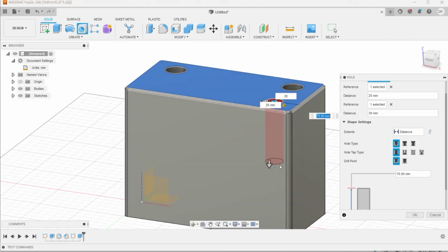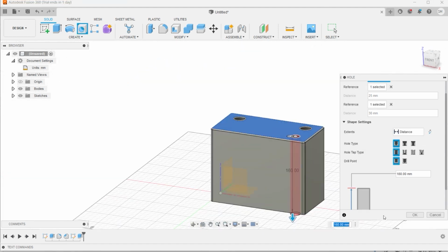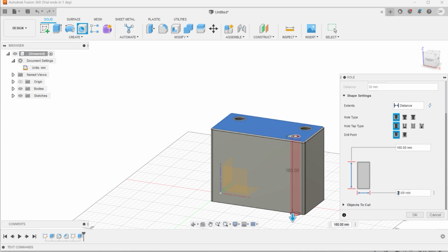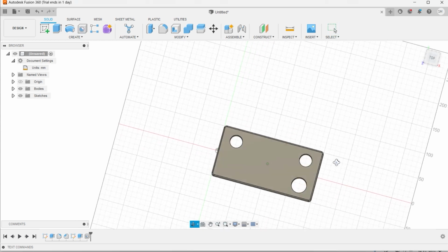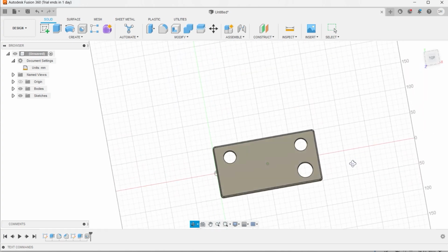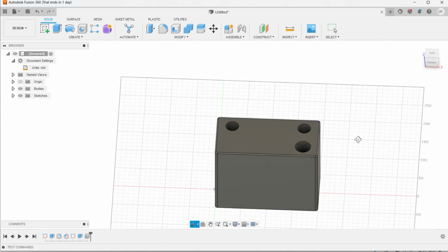So what we'll do is we can drag it down so it is a direct hole. Now we can change the diameter also as per our requirement, right? Suppose this one is 30 millimeter. Okay, the hole is made already, right? This is a ready-made hole, and it can be provided as per our requirement at any location, right?